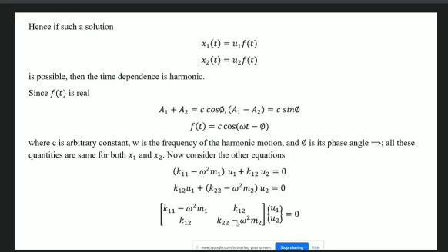We considered the free vibration equation. That means the force vectors we considered as a null vector, and then also we got rid of the damping, and then ultimately while considering modal vibration, that means vibration which is taking place in a particular mode, we discussed the fact that the shape remains constant, but the amplitude may change depending on the initial conditions or depending on the loading functions, whatever it is.